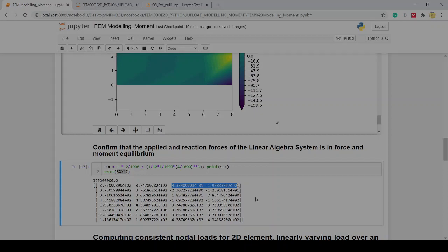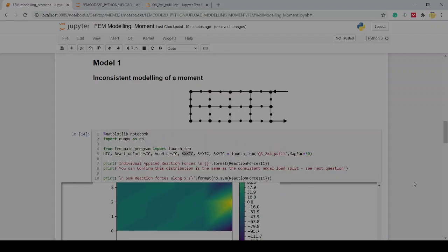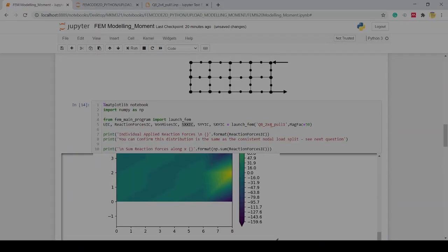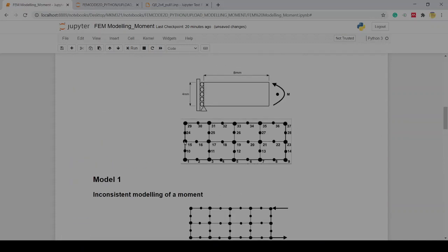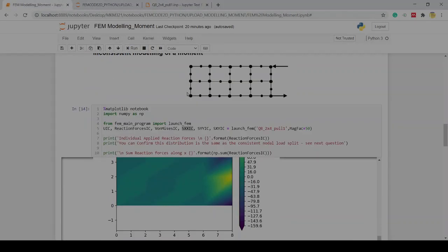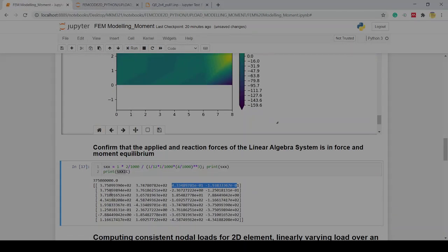That's all good and well. I can also check this other element, the one that's in tension, at the top, this one here. So it's 15, 17, 31, 29. That's element number 5, or the 4th index, the 5th one down that list, so that's what we're going to be looking at. If I go down this list, the 5th one: 1, 2, 3, 4, 5.